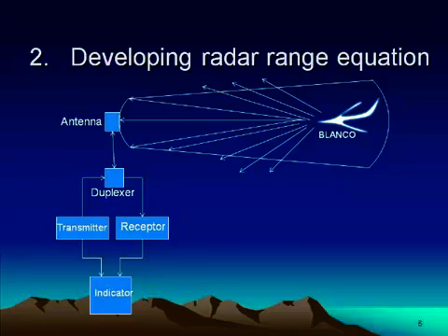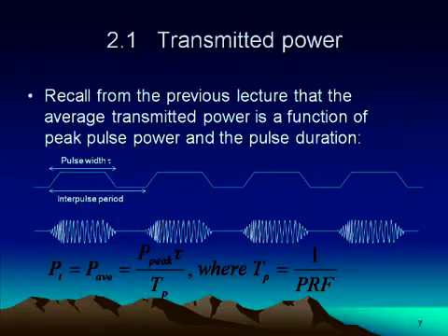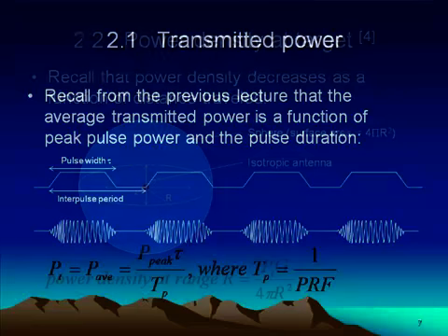Here we are going to see that depending on the transmitter pulse width and the height, we can find out how much transmitter power on an average is being sent. Why we are saying on an average is, when the pulse is on, it is only for a short duration. Most of the time in the cycle there is no power transmission. The radar will be waiting for the received signal. So average power is taken into account for this calculation.